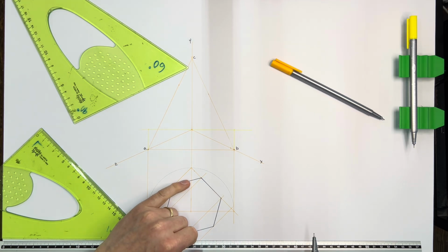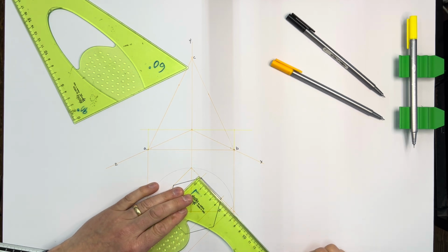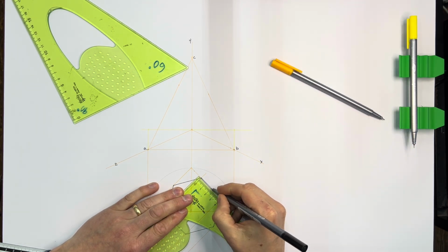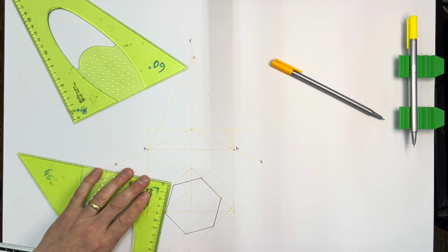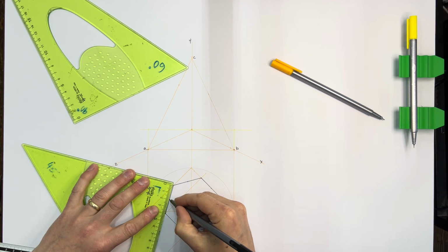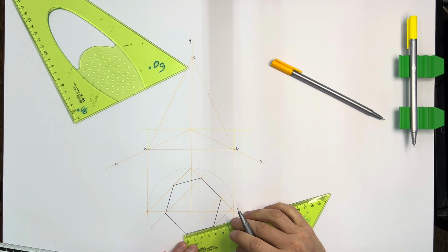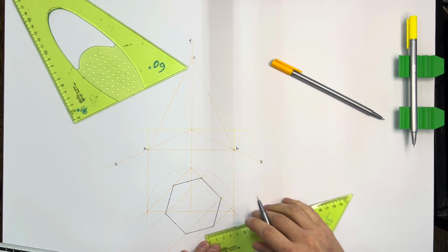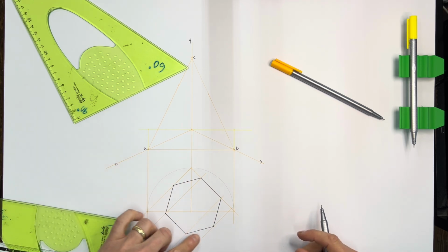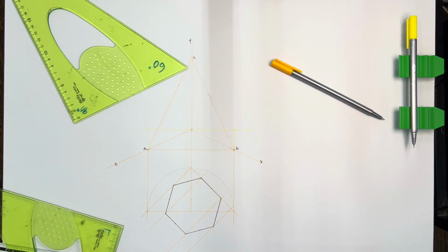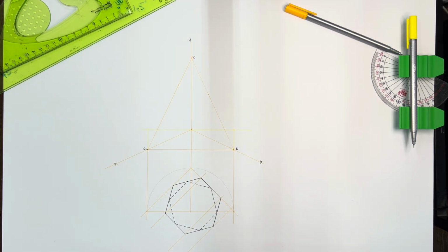Okay, so there is another hidden detail hexagon on the inside of that. Each length of side should be 40 millimeters. So the quickest, most efficient way of doing this is just mark 20 millimeters across each length of side, simply getting the midpoint of each side. Okay, and I'm just going to pause the video here, and I'm just going to use hidden detail to draw my internal hexagon. So that's the plan complete. That's what it looks like. Now, moving on to the elevation.